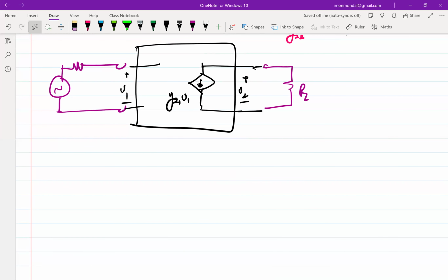So now that we understand, at least in the incremental sense, what the requirements are, the whole purpose of this is to design the final nonlinear block. It's not like we can stop the course just because we understand the requirements of a Y parameter. Ultimately, Y parameter is a model, but as a designer, you cannot give a model to the user. You have to give a full block. So we need to understand what the actual total IV characteristics, not the differential, not the incremental, should look like when we want to design this entire loop. Let's take a step forward and see how we can build up the IV characteristics of an amplifier that we would like it to have.